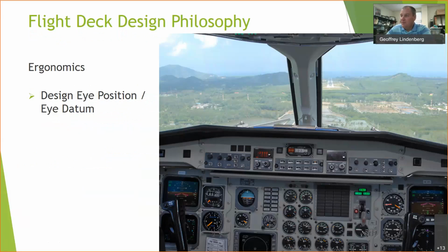So when we're designing it, one of the big things is looking at eye level and knowing what the eye datum is. We want everyone sitting in a flight deck to have the same view, and we need to understand that. The reason this is important for maintenance technicians is many of you are going to operate the aircraft from a standpoint that maybe you won't fly it, but you'll definitely taxi it. You'll need to move it from the gate to the hangar, from gate to gate, whatnot.